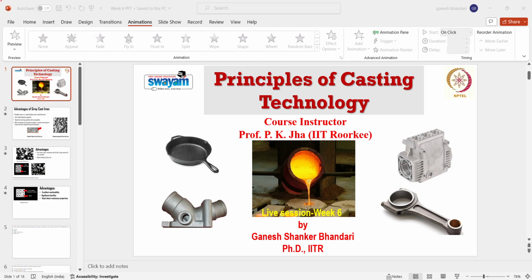Yes. In grey cast iron, we talk about flake type of graphite, and the tempered carbon is generally present in your malleable cast iron. Combined form as cementite, Fe3C, is present in your white cast iron. And the granular type of graphite is present in the nodular cast iron, or ductile cast iron. Your graphite carbon is present in the nodular form.